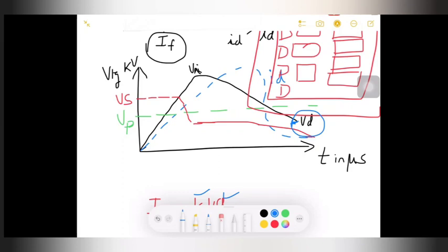And this provides protection for the operators above the protection level Vp. Vp is the protection level that has been taken. That is a minimum value, we can say the preset value, so whatever fault occurs should be within that limit. If you observe, ID and Vs, the operating voltage, are below this green line. Hence it will operate within the protection level. Hence we can say the surge arrestor is protecting the operators or any transmission line or any equipment within a power system. So this is regarding the surge arrestor.